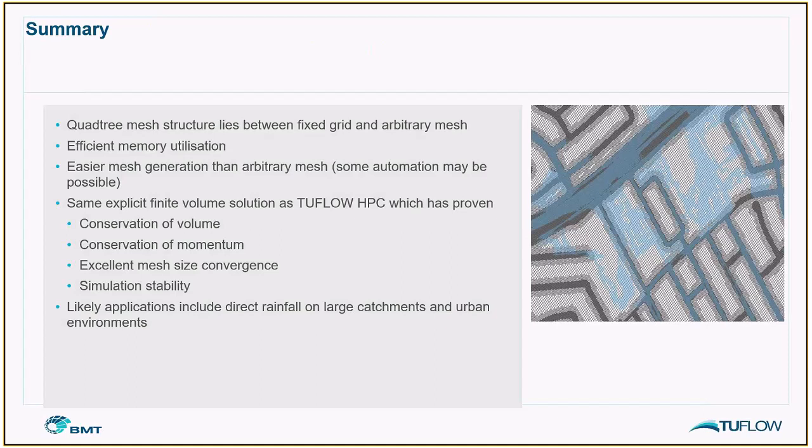The application for TUFLOW Quadtree is for users in urban environments, particularly direct rainfall, where users are likely to represent the detail on road surfaces, to represent primary flow routes and also drainage features, but also applications to large catchment modelling, where again quite often direct rainfall is applied, where users will want to represent the detail with natural drainage features. So thank you very much for listening, and I'm happy to take any questions.